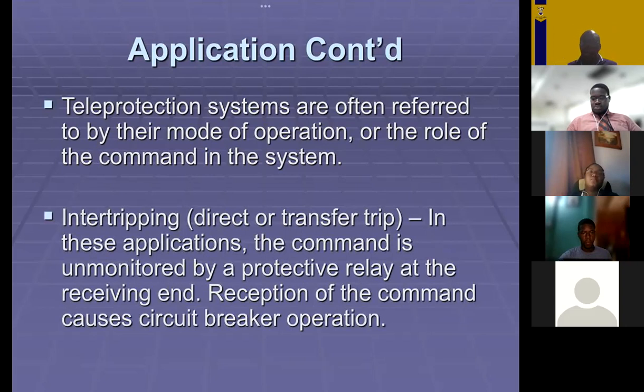We will call it intertripping or direct transfer trip, because the command, which is unmonitored, allows or causes circuit breaker operation. So the mode of operation is unsupervised receipt of a trip signal via your medium.